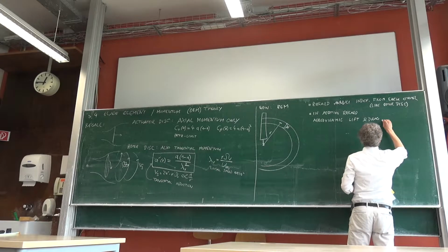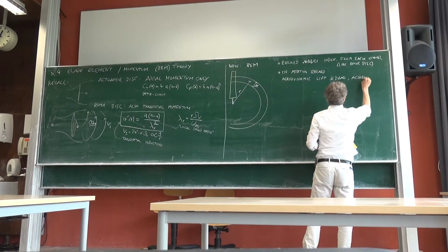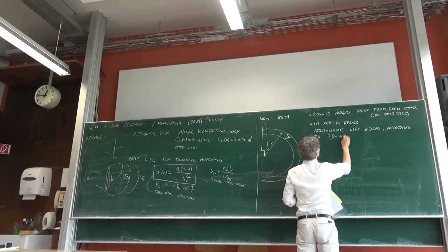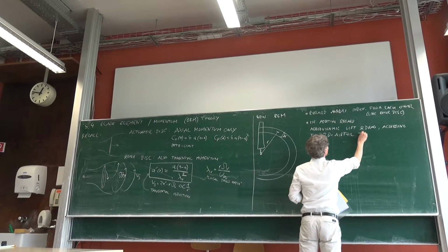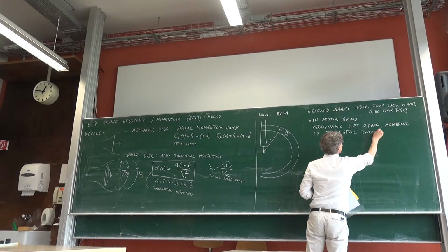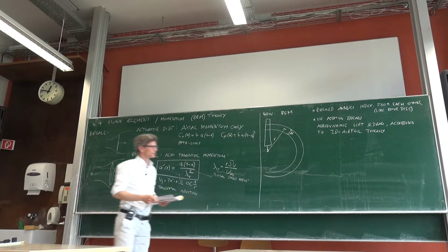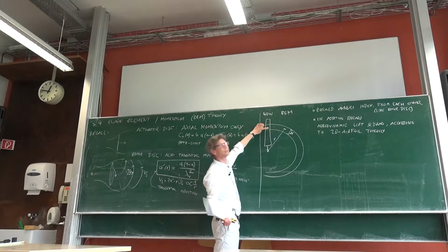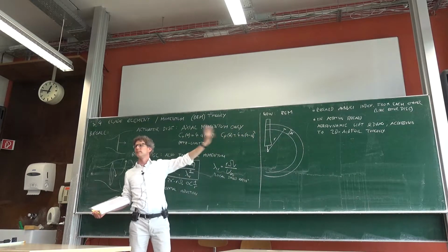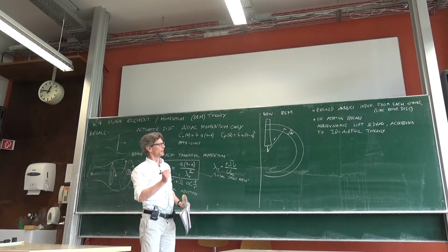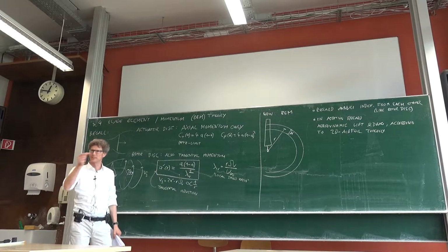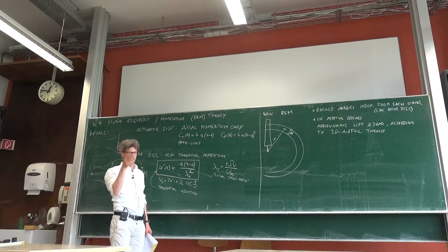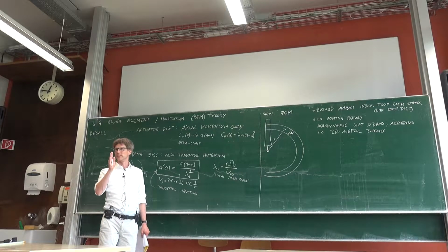But we assume two-dimensional airfoils. 2D airfoil. And so we will make the assumption, so to say, that each of these blade elements, that's a blade element, behaves completely independent to the others and has basically an aerodynamic lift and a drag that corresponds to its cross-sectional area, I mean the shape, and to the angle of attack, of course, that it has.